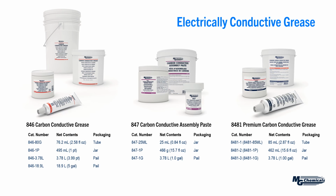So we have the 846, which is an electrically conductive grease. That's a lubricating grease. Conversely, the 847 carbon conductive assembly paste, we don't really market as a grease. It doesn't provide a whole lot of lubrication. This has a higher filler level, so it is more of a paste instead, meaning it really doesn't perform lubricating functions. And then the 8481 is a premium carbon conductive grease, and that was formulated for enhanced corrosion protection. And again, available in larger tub sizes and tubes.